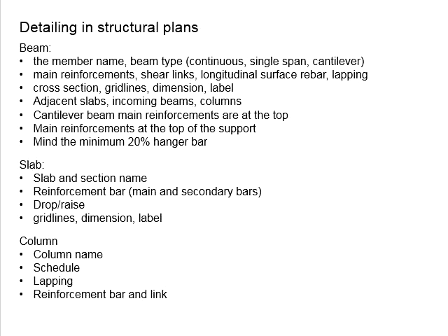There will also be columns, which we mentioned just now. The dimensions need to be correct. Whether there are columns penetrating above the beam needs to be clearly indicated, and sometimes the existence of the stiffener needs to be clearly indicated as well.